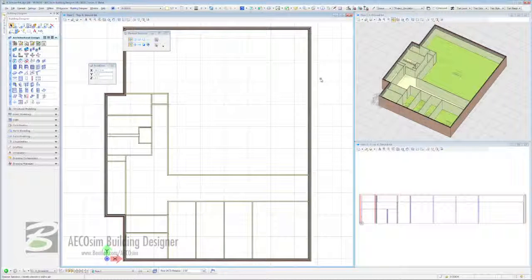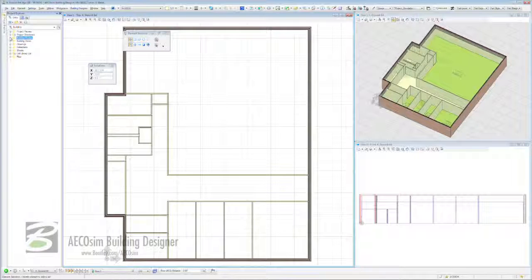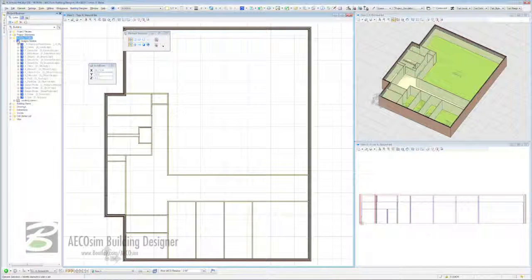After that, we're going to start really flexing the back office muscles of Building Designer, because instead of going through and recreating material and data, we're going to use material that was there before. What do I mean? Quite simply, do you remember the architectural master file that we created? We're going to be using its technical data to help us out with the placement of doors and windows. How? Let's go across to Project Explorer next to our task-based interface, and in there, come to Building Models and twirl that down, and twirl down Design Models. Then come down to Underbar Master Low-Rise Scheme, right-click on that and say Place Model.